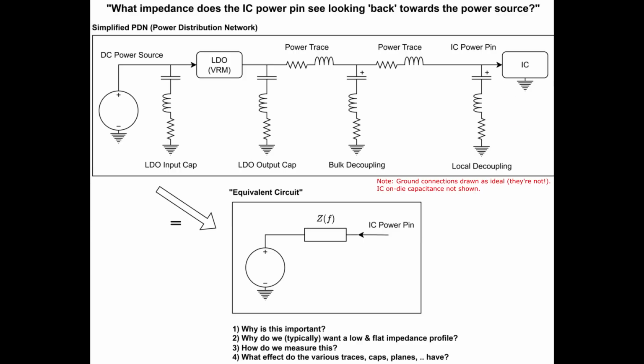Keep in mind, this is incredibly simplified. I've just shown this for one single VCC connection. I'm not showing the non-ideal ground connections. I'm showing simplified models of the capacitors and inductors and so on, but this is just to get the basics. These kinds of structures can be extracted from pretty much any PCB, any power distribution network, and this is exactly what this is. This is the distribution of power, how we get from the power source to an adequate voltage and feed that into the IC, which has certain current and voltage and power demands.